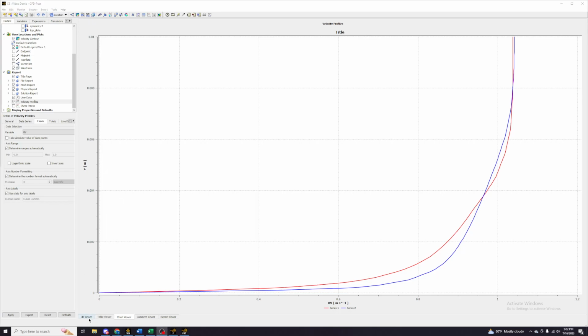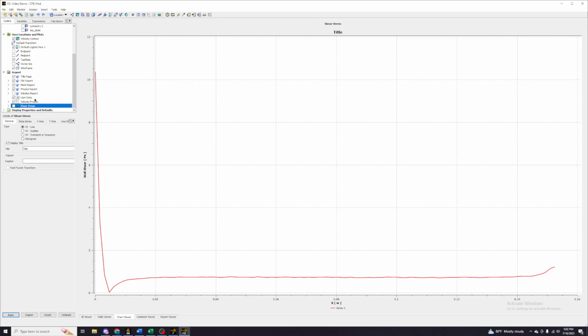Also, if there's anything else, you basically just export all of your files for further calculations, and you can figure out your Reynolds numbers. You can figure out the wall shear stress, the local skin friction coefficient, your drag force coefficient, so all of those things through either post ANSYS or within Fluent itself.